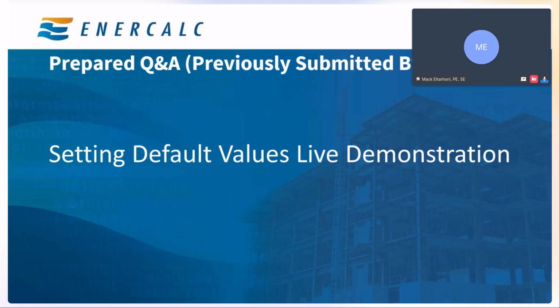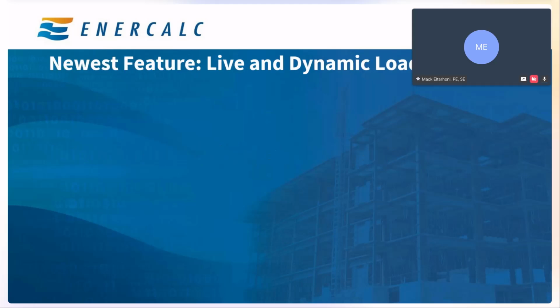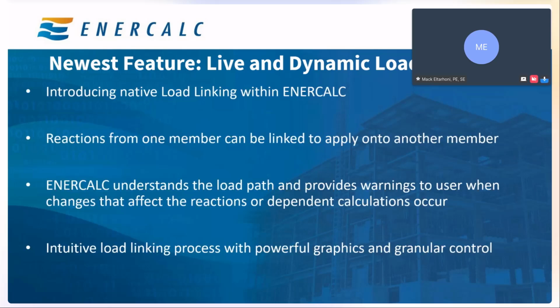So now we move on to our next part of the presentation, and that is live and dynamic load linking. ENERCALC's newest build includes a new feature introduced in the steel beam module, and this is load linking. Load linking is now a native feature within ENERCALC. You can take reactions from one member and link them to apply onto another member.